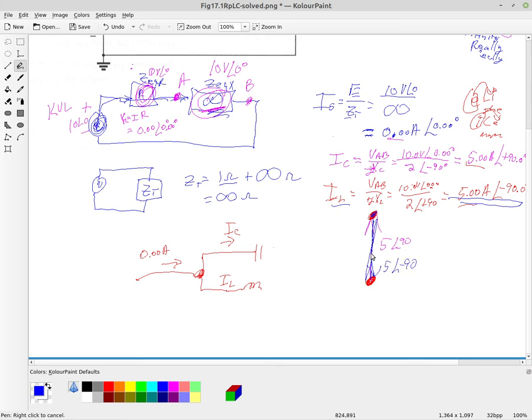So as I said before, these guys are basically just sitting here playing hot potato, passing their energy back and forth between them. So our total current is, as we calculated, right, we have plus 5 going straight up, and then 5 coming straight down. So our total current is actually 0. Okay. And so that is verified by Kirchhoff's current law, KCL.